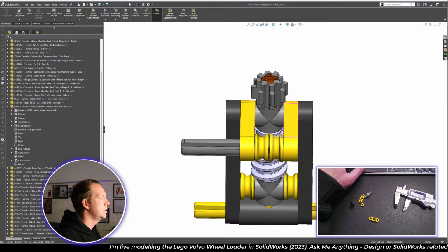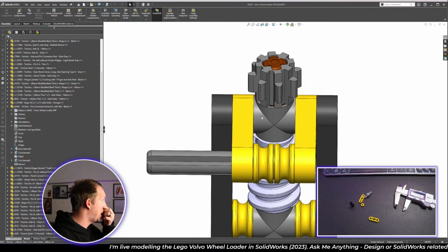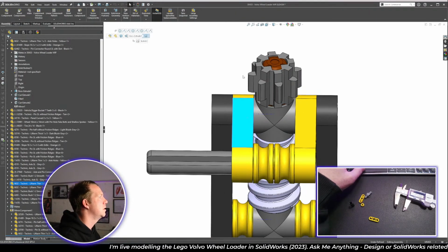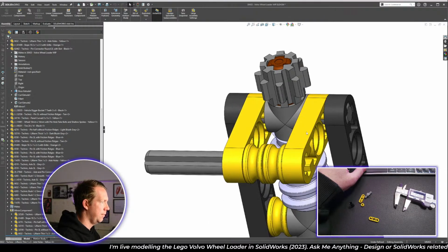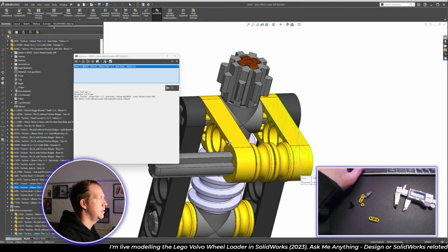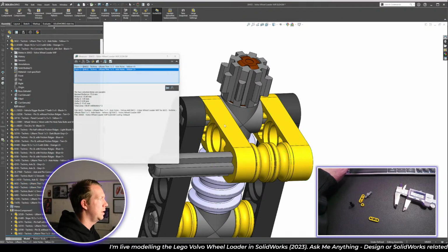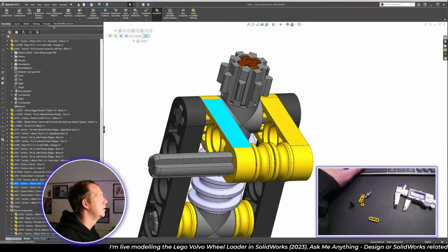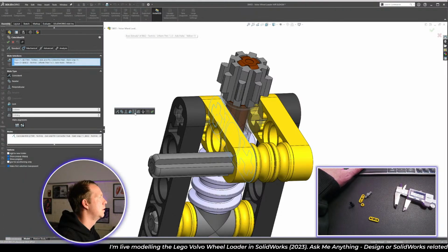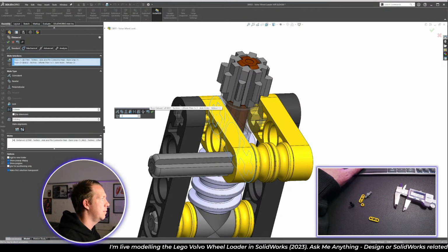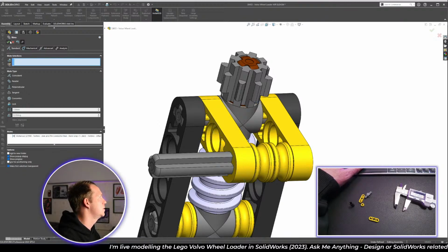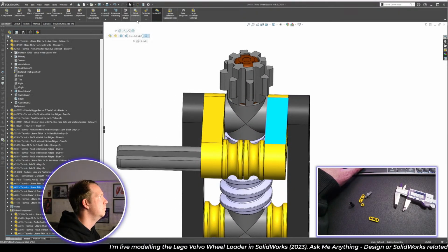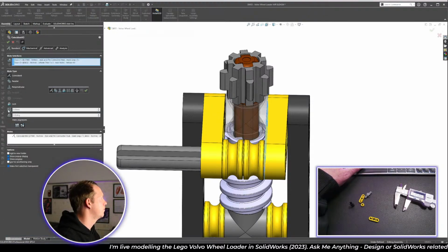All right, so perhaps I just need to add a bit of clearance in here. So this, let's say from like this face to this face, should be another 0.1 further. So I can look at the mate that's there, and I can say, okay, there might be a 0.1mm space, and there might be a 0.1mm space on this one.